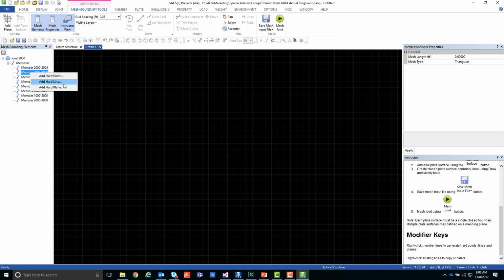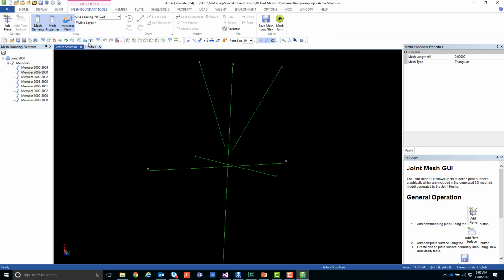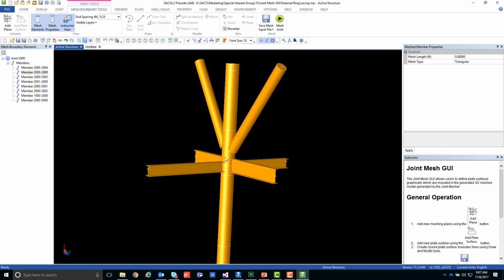And this is useful if you're going to do things like delete elements after you create the mesh, if you're planning on modifying it after doing the mesh. It's also going to be used for applications like extracting SCFs. That's really the main application for this. We want to be able to use automatic SCFs extraction, which the developers are still working on, but when we get that, those will be used for that application.